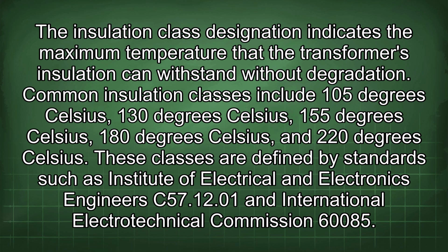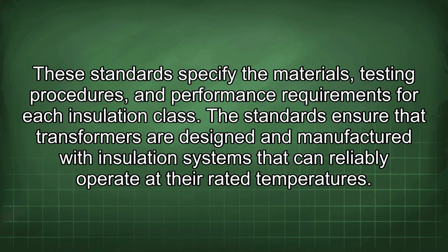These classes are defined by standards such as Institute of Electrical and Electronics Engineers C57.12-1 and International Electrotechnical Commission 60085. These standards specify the materials, testing procedures, and performance requirements for each insulation class. The standards ensure that transformers are designed and manufactured with insulation systems that can reliably operate at their rated temperatures.